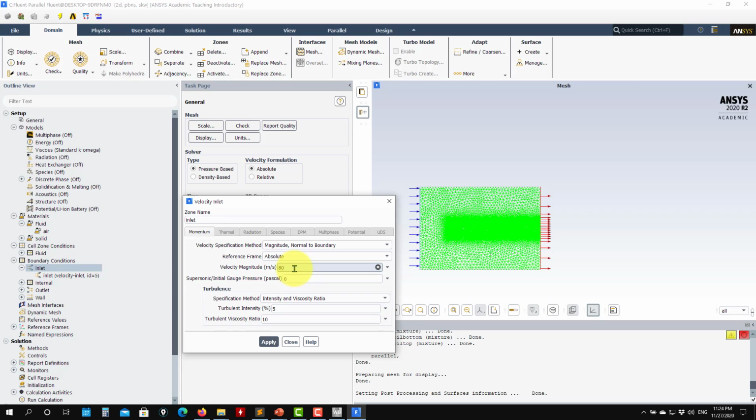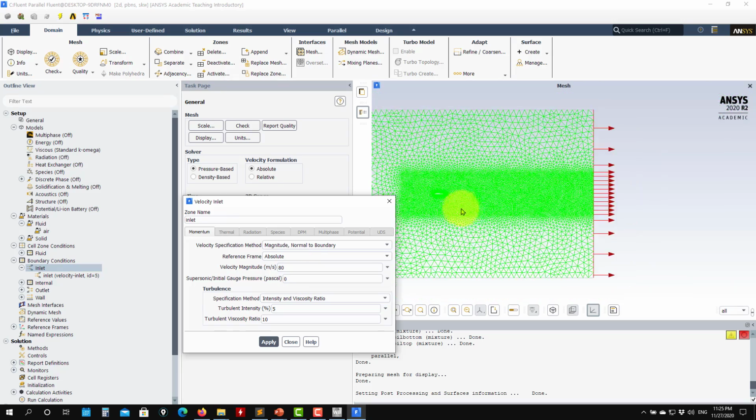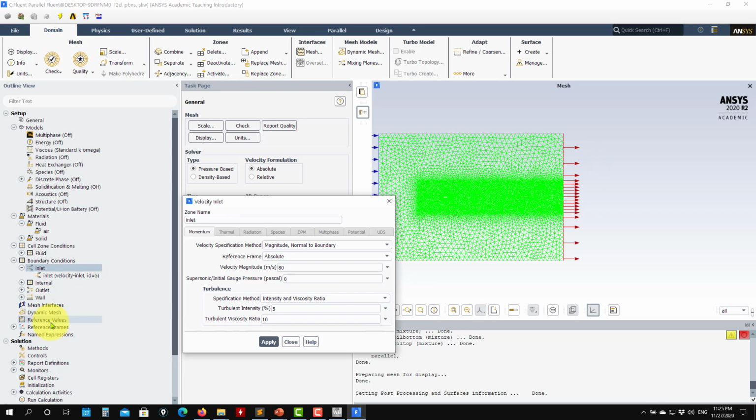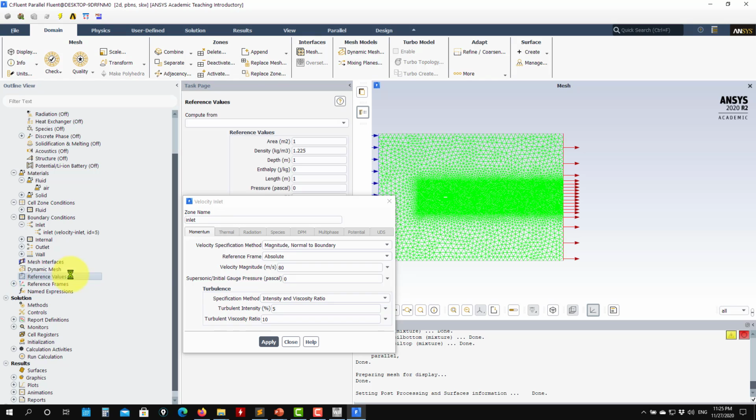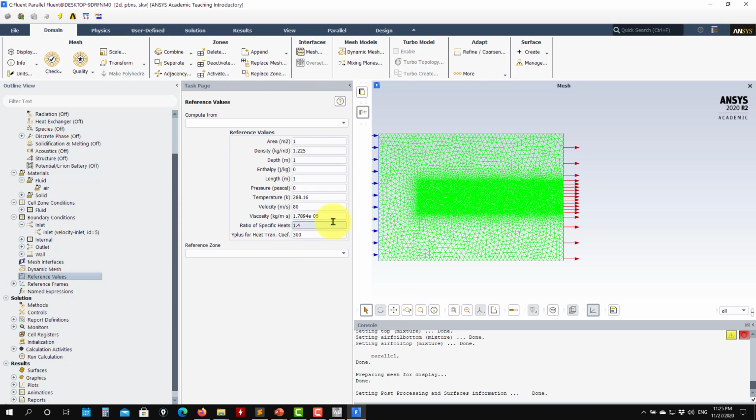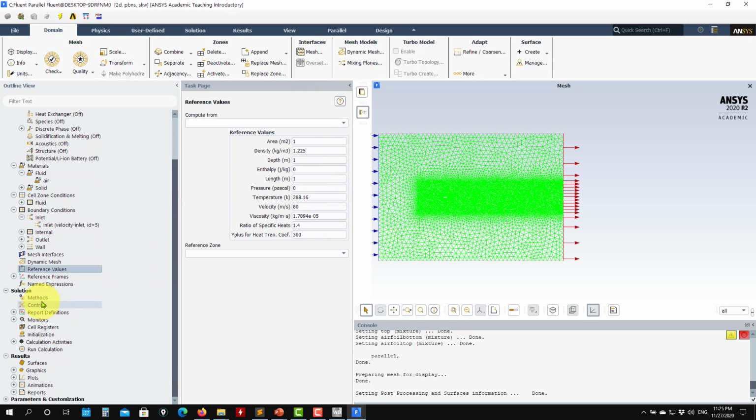But here it's not like previously, where sometimes we don't give anything. With a full implicit solution, you don't give anything, and you get your 2 pi for this lift curve. But here you need to give the velocity value. This is a viscous solution. The outlet, and see how complicated it is. Then you give options. These are reference values to compute coefficients if you want to compute coefficients.